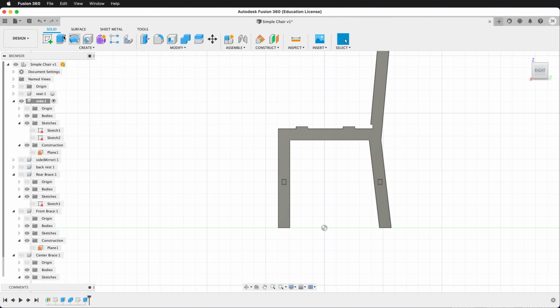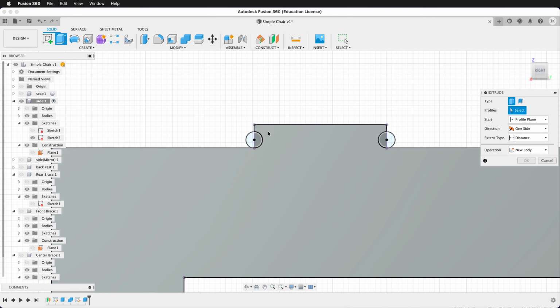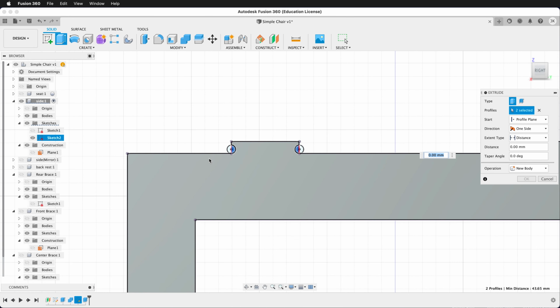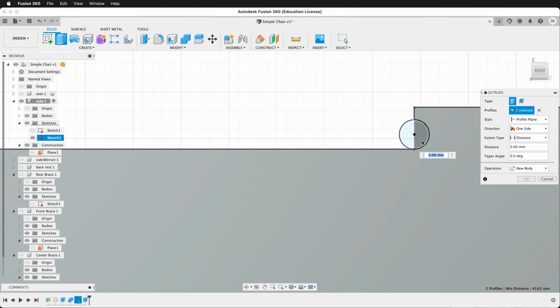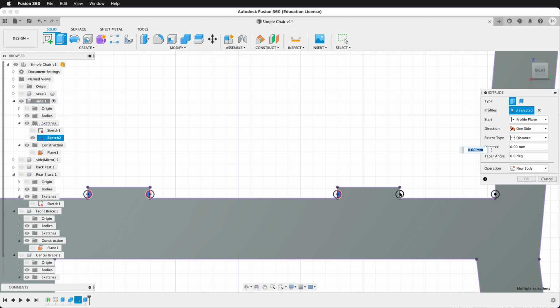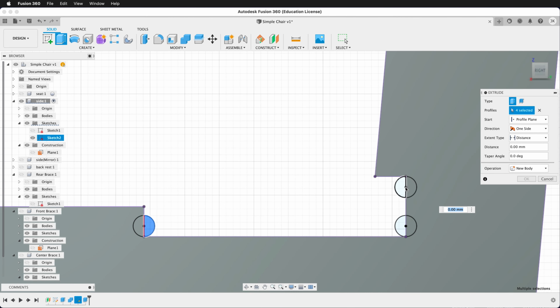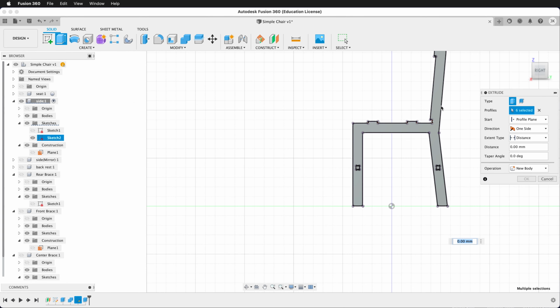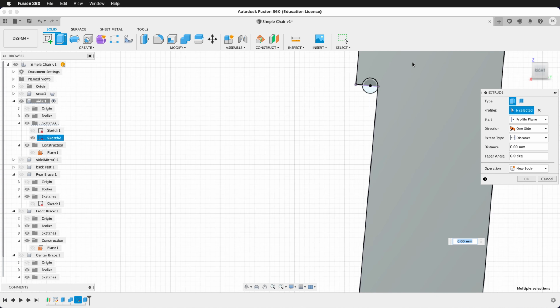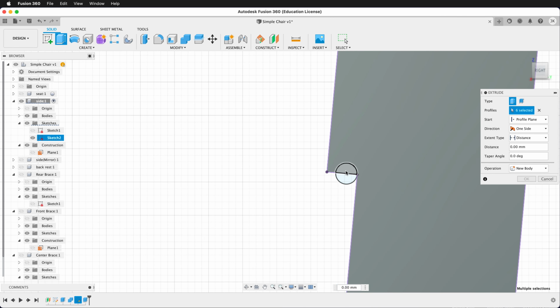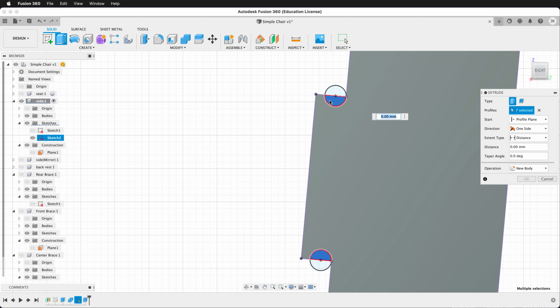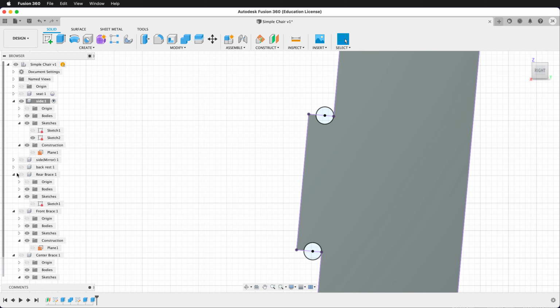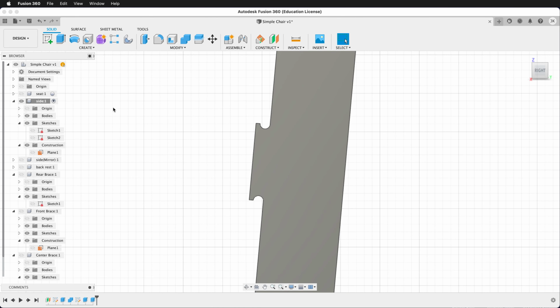Let's do the extrusion again. And this time we need to show sketch number 2, so we can see the profiles. Click this one on that tab, and on this tab. And we need the 2 right here. And then finally up at the backrest tab. And these ones will go the full dimension of ply, but it'll be negative ply. So now all those are cut out, and then we can hide our sketch.